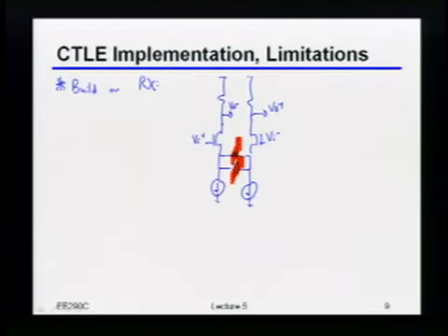There's actually a couple more issues. What else do you think? Yeah. You can only get a 20 dB per decade increase. I mean, if it's more than that. Okay, so you said you can only get 20 dB per decade. The issue I'm getting at is closely related to that. But what if I said, no, fine, I really want you to do more than 20 dB per decade? What do you have to do?